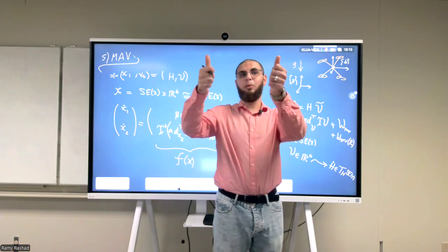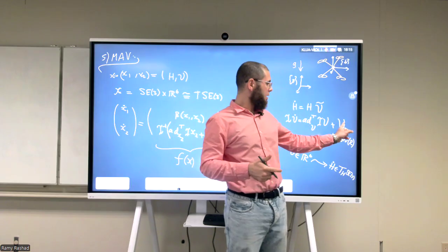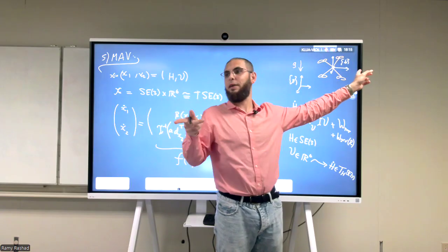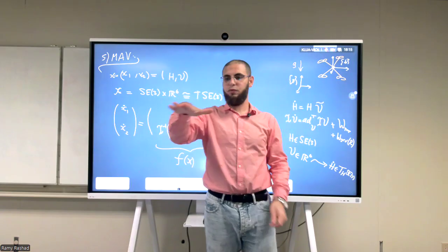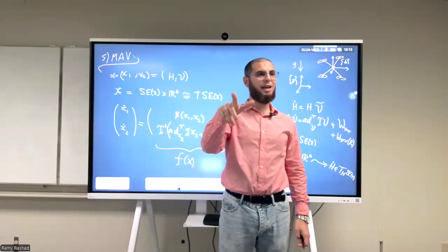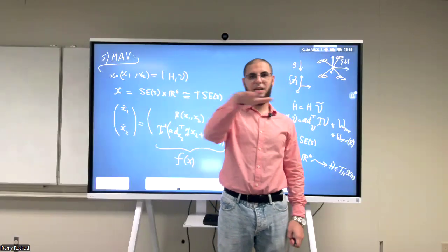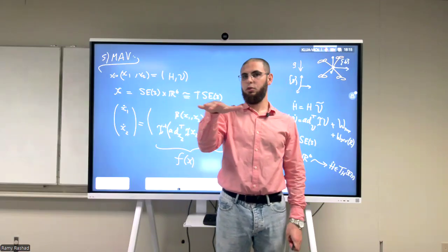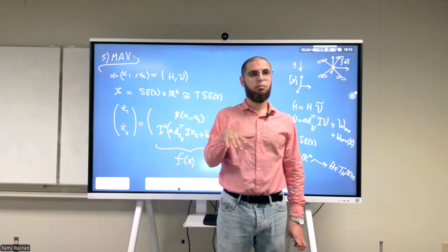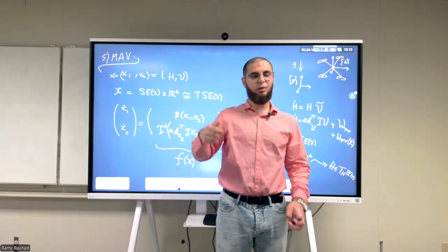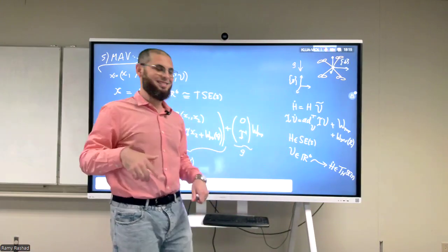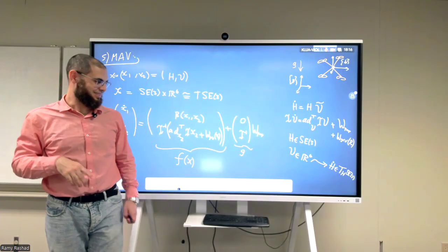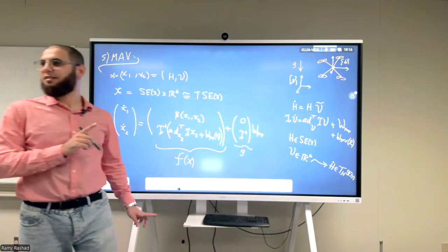If you make all of the propellers point upward, then some directions, the horizontal directions X and Y, you're not going to be able to affect. This is one of the reasons why the quad rotor cannot move sideways like this. The guys that have the fully actuated hexarotor will be able to move it sideways like this. There are also some videos online for the same drone. The one in the lab, you mean? We haven't made it fully actuated yet. The guys working on it are doing it. Okay, I'll tell them. Any more questions?